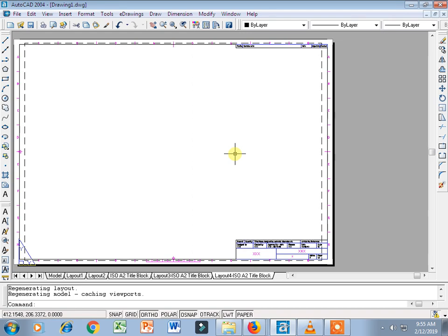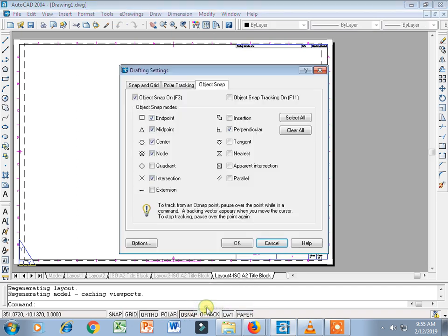We will learn how to draw a problem for isometric projection. Before starting with the isometric projection, we have to do some settings. Right now the grid available is a rectangular grid. We have to convert it to isogrid. So we will go to OSnap settings.